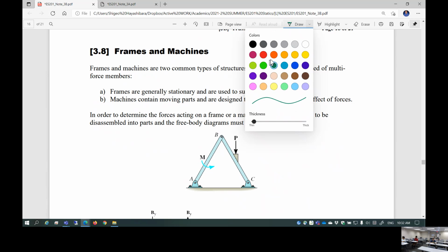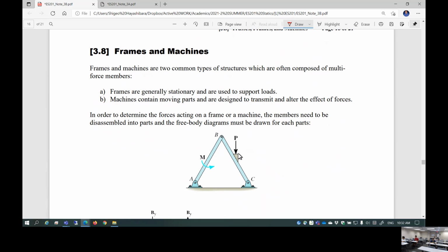Suppose you want to apply the force P right here. This is otherwise a truss member, but you're going to have both pin supports. Oh my goodness, both pin supports. This actually has 4 unknowns. Pin supports A and C, and then this is some kind of, I don't know, rigid surface. You apply the force P here on member BC, and also this is a bend. This is called a bending moment. The moment is applied to member AB in the middle.